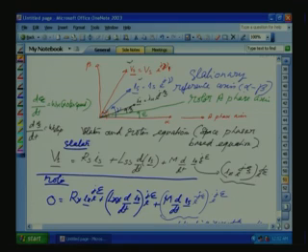Now, this is the voltage. This voltage also we want to bring to the stator, so we are multiplying by e^(jε). Now, there is a current term which is originally defined with respect to the stator axis, that will induce a voltage in the rotor. So, this current originally defined with the stator axis has to be defined with respect to the rotor axis. So, from here it has to go here. So, e^(−jε), then d/dt of I_S, this is the voltage term induced at the rotor.